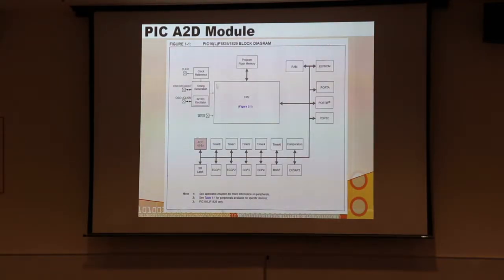And then, because it's a Harvard machine, we also have program memory sitting out here on a separate bus, 14 bits wide of data, a bigger address bus, 15 bits of address bus, 14 bits of a data bus. Here we have 8-bit data bus and only a 12-bit address bus. The upper 5 bits come from the BSR, lower 7 come from the instruction when you're direct addressing, and then if you're using indirect addressing, you get 16 bits from the indirect registers, of which you only need 12 at the end.